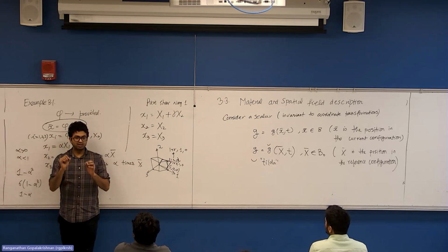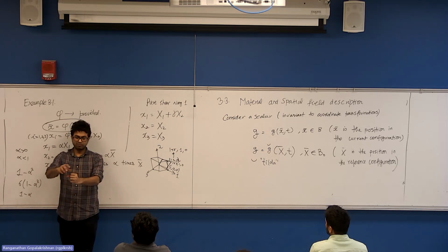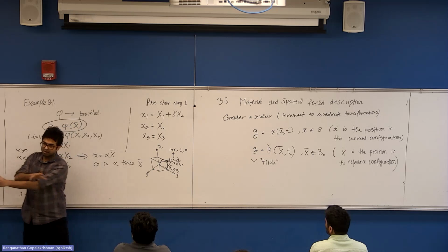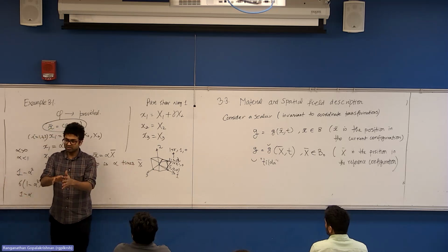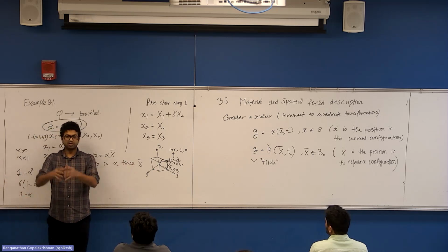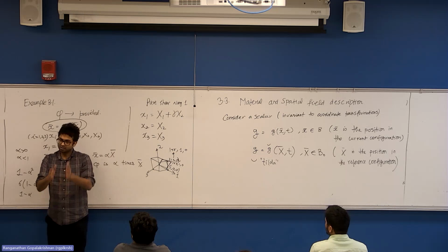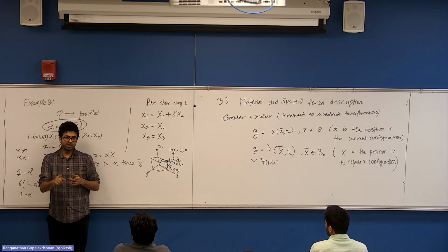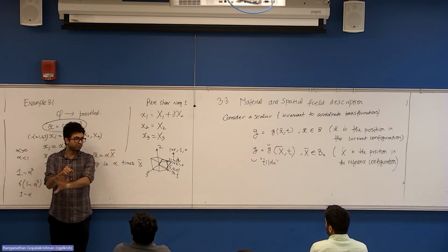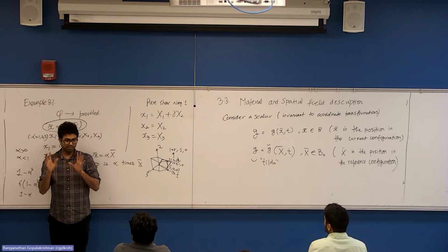You are getting the velocity of one particular point in your flow field. At one instant, there are a bunch of molecules occupying that zone. The next instant, they are gone. Some other batch walks in and you are measuring the velocity of that batch. Gone. Again, another measurement, gone. So you are interested in the velocity of the fluid at that location in space, not necessarily for the same set of molecules. Does that make sense?